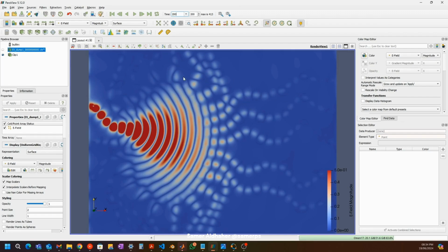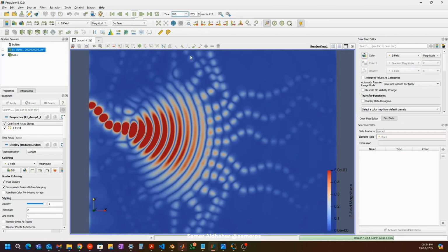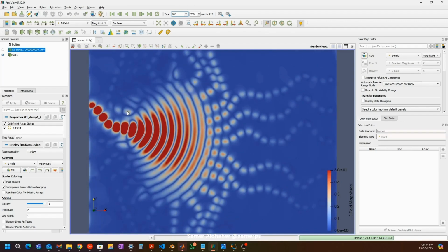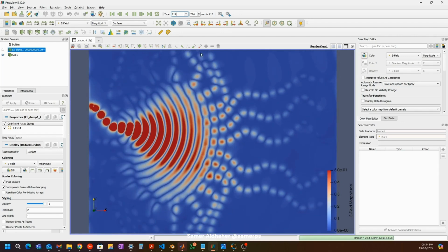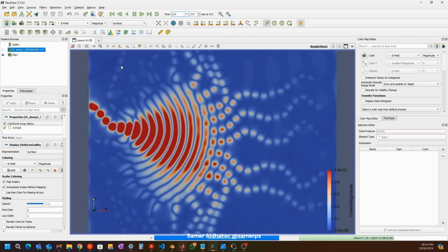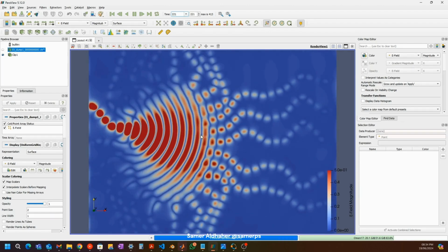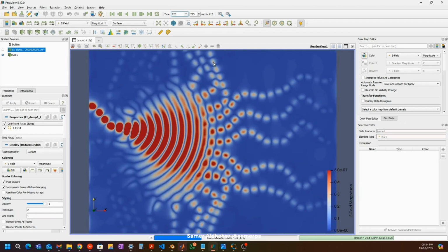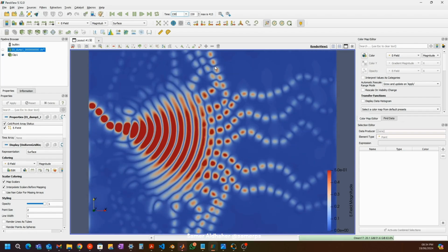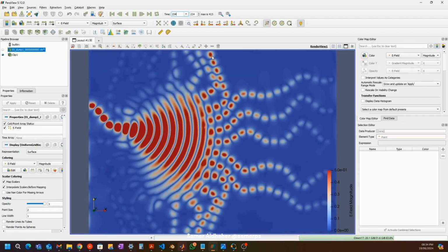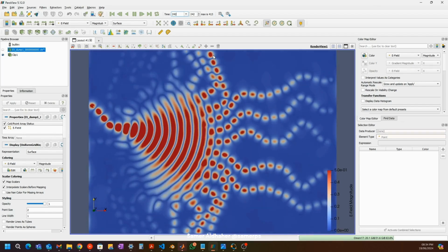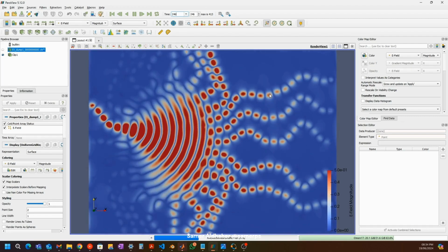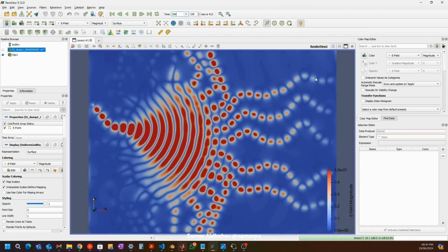And theoretically, what should happen is all these dummy ports, so we should see no reflections, or all the waves should be absorbed. And perhaps here, all these waves are traveling mostly here and not much on these traces that are close to the input. So far things look okay. We start now to see some standing waves that are forming, probably due to the mismatch. It could be due to the mesh or the geometry itself, the dielectric properties that we set. But so far it's looking okay, and you can see here these waves are traveling, no standing waves so far.